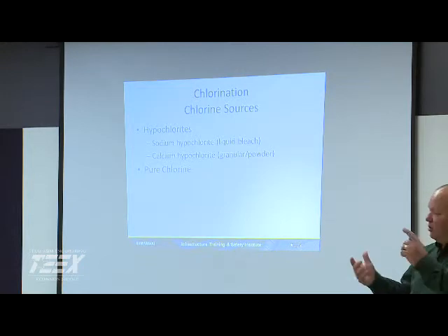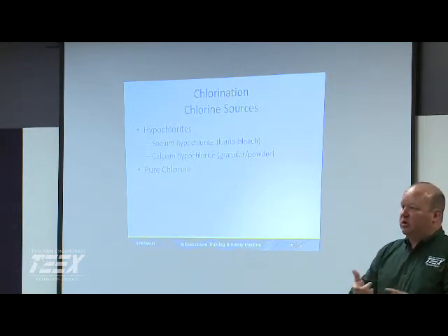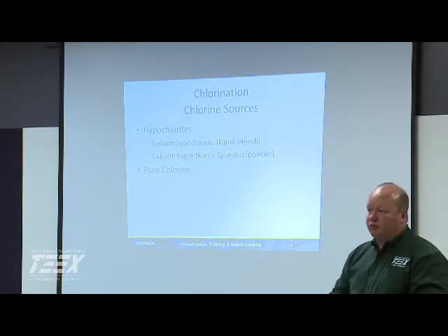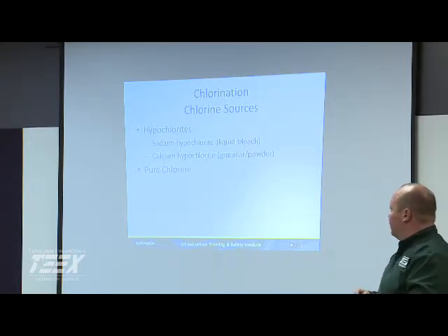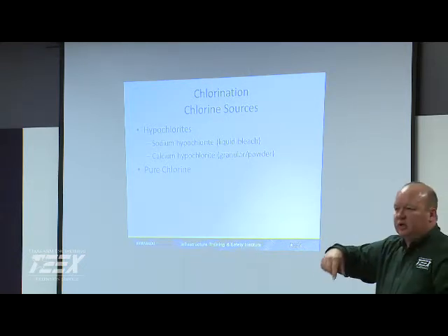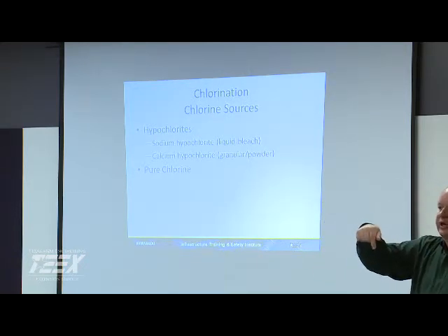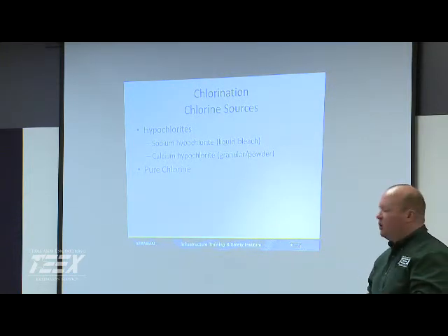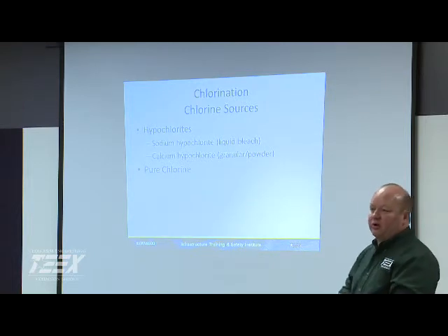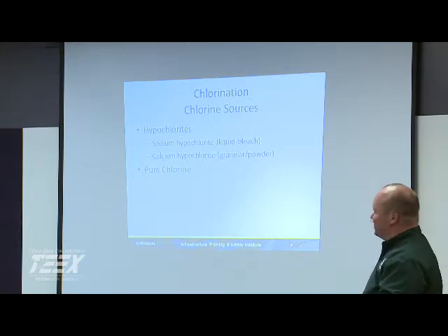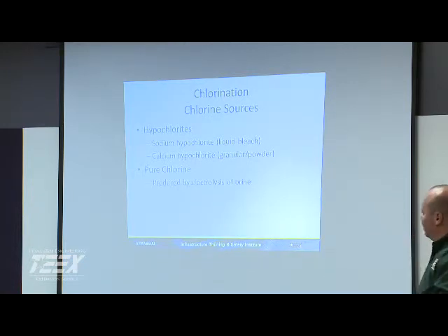Anything that goes into the water or can potentially be in contact with the water, any kinds of oils, bleach, anything else, needs to be NSF approved food grade. Because otherwise, on our SCU, our solid contact unit, we had a big chain drive for our rake system, and they put in a drip system to lubricate it. Well, you gotta make sure, because anytime it rains, it's gonna be right down into your water. So we had to make sure we had food grade, you know, we just couldn't go buy whatever somebody found cheap at the store to put in there.